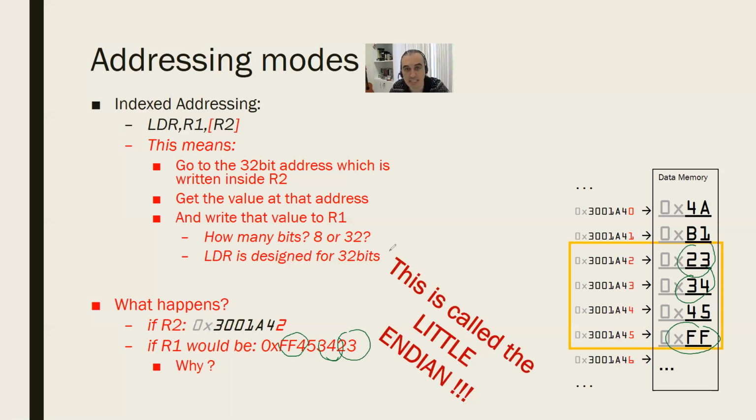I'm going to make an exception only for once and show you what big endian is so that you could understand little endian. Our system is little endian. But if our system was big endian, then this code would provide an R1 value that is the opposite.